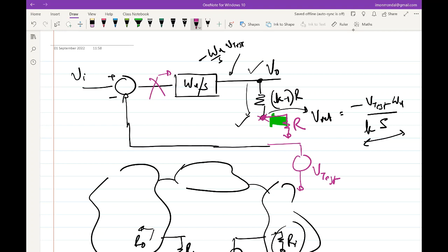And truly speaking, when you are designing circuits with transistors, there is no node which is exactly infinite impedance, because even if you are seeing the gate of a transistor, you are seeing some capacitance. At high frequencies, capacitance will also draw current. So strictly speaking, you have to translate that capacitance on the other side also. But those are discussions for another course. We'll not get into that.